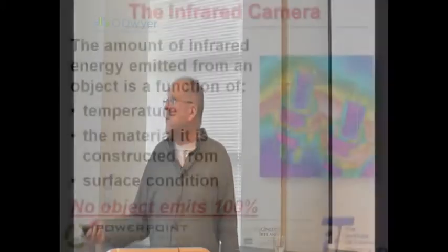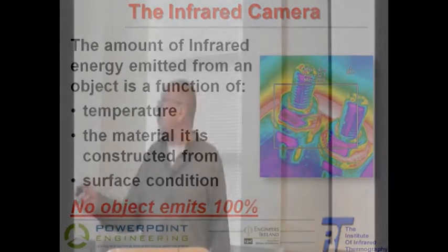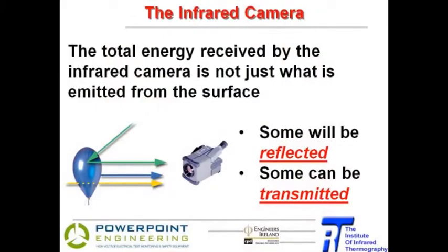And what a lot of thermographers do if they don't have training is they'll look at an image like that and assume that there's temperature variation in there when there isn't. That's down to changes in emissivity. And unfortunately, metal components have very low emissivity, and they reflect a lot of the background. So in this particular case, that area there, which appears to be much colder, 20.8 degrees there, is actually reflecting the background temperature of the area in which it's in. The highest temperature that's being recorded there, which is 42, is more likely the actual temperature of all of that connection. But differences in emissivity can cause false readings or false anomalies, which you need to account for.